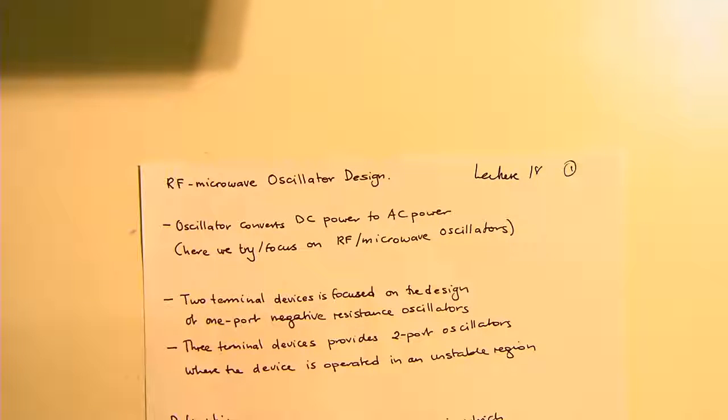But the signal here, before we transmit it, we want to be transmitting at, for argument's sake, say 2.4 gig, or 60 gig. At 60 gig, you're at AMD building these transceivers operating at 60 gig because you're trying to get wireless VR. So this signal here has to be at 60 gig. The DAC is producing a signal, for argument's sake, at 800 megahertz. So how do I go from 800 megahertz to 60 gigahertz?